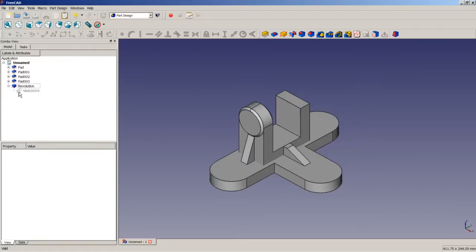So in FreeCAD you have a possibility to copy the sketch or something else to the clipboard and paste it in again to reuse it. But there is one limitation. In FreeCAD you can only copy 2 instances of a 3D operation to the clipboard, not more.